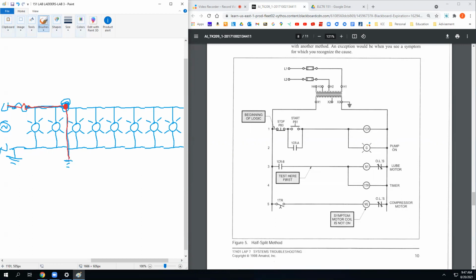So is there anything stopping current flow? Are there any lights in there? No. So you're direct shorting this to ground because of this ground fault. Okay? So there's nothing limiting current there. It's causing the fuse to blow. Anything over 30 amps will cause that fuse to blow. So somewhere in this system, there's a ground fault that looks like that. How do we know where?